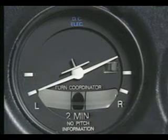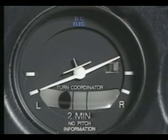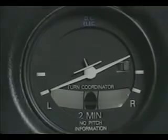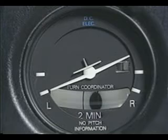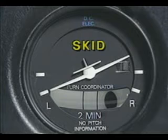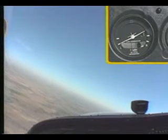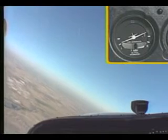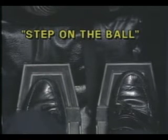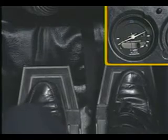However, if the bank becomes too steep for the turn rate, the ball will move to the inside of the turn and indicate a slip. If the bank is too shallow for the turn rate, the ball will move to the outside of the turn, indicating the airplane is in a skid. You can center the ball by varying your angle of bank, or by applying rudder pressure in the direction of the deflected ball. To help you determine which rudder pedal to press, use the saying, "Step on the ball." In other words, if the ball is out to the right, step on the right rudder pedal.